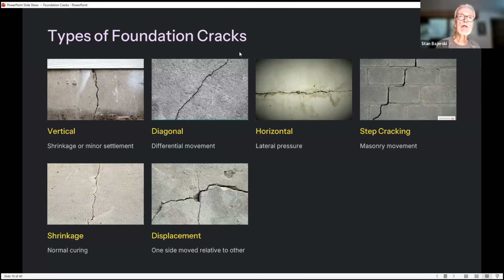So they're in different locations. Also has a lot to do with what's going on and the soil conditions as well. And a lot of these cracks could have been caused during backfill. These guys go a little nuts. They might have a stump in the soil, pushing it against the house. That's still green material. So there's a lot of different reasons why you may see these things when you're doing your home inspection. Okay, Jim.